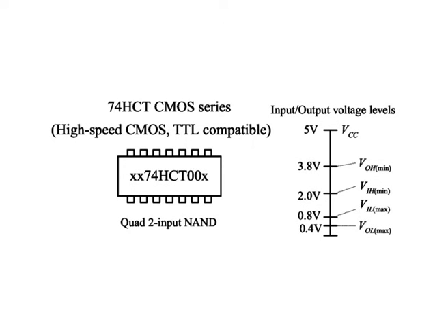Like the 74HC CMOS series, the 74HCT CMOS series is an improvement in speed over the 4000 CMOS series. As speedy as the 74LS TTL series, depending on the operating frequency, it also provides greater noise immunity and greater voltage and temperature operating ranges than TTL.